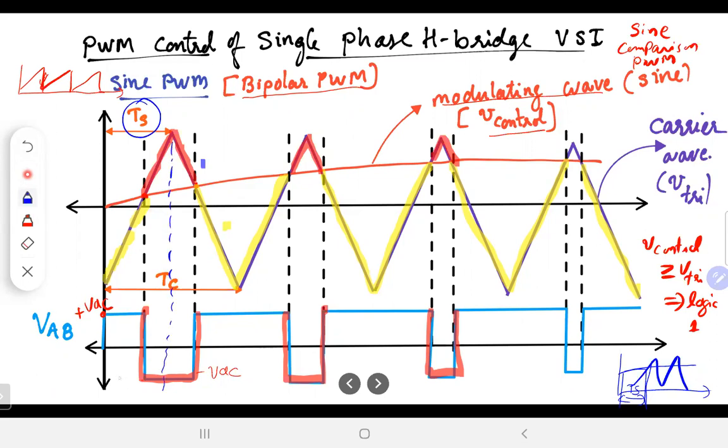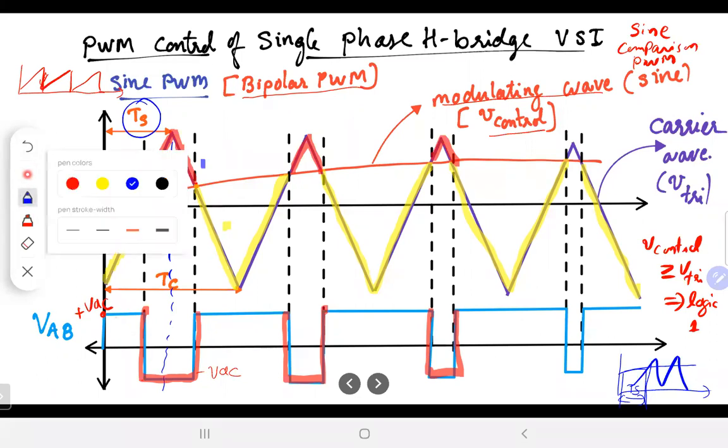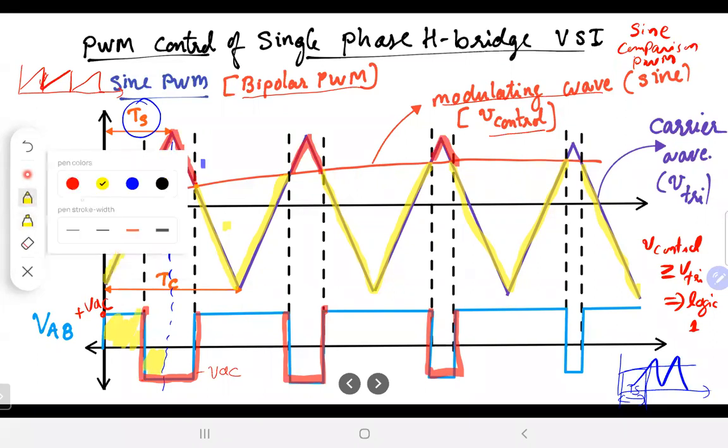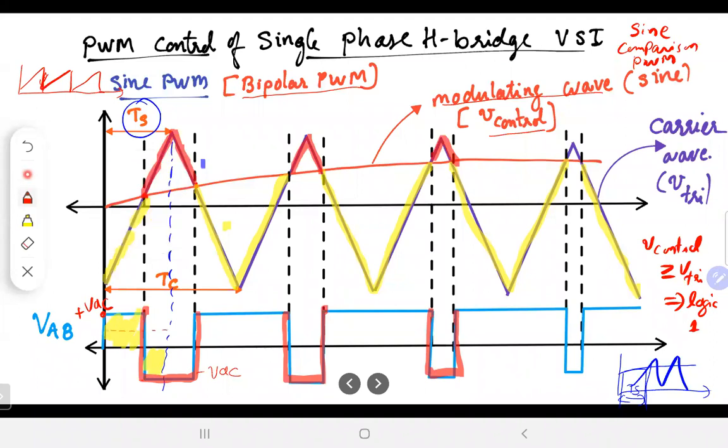So if you look at the volt second here, I would have got some positive here in this region, and I would have had some negative in this region. Whatever is the resultant would have given me an equivalent voltage. We see that the positive region is a little higher, the negative region is a little lower, so I would have got some non-zero pulse here in the first half cycle. In the next half cycle, again, you have a similar thing.